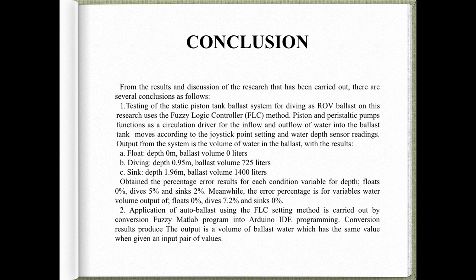So the conclusion of this result is testing of the static piston tank ballast system for diving as ROV ballast in this research using the fuzzy logic controller method. Piston and joystick pump function as circulation drivers for the inflow and outflow of water into the ballast tank, moving according to joystick point setting and water depth sensor reading.